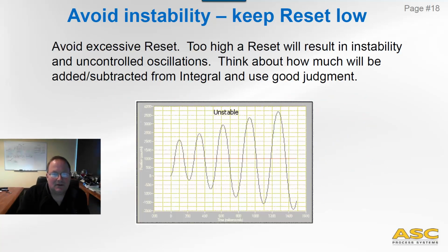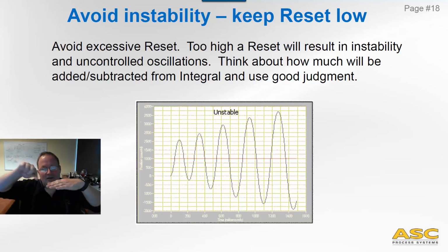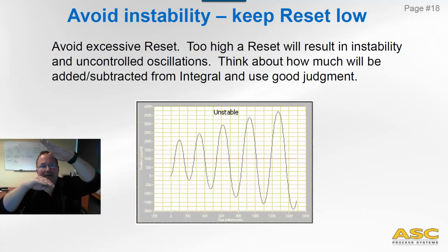What's another consideration? Keep your reset low. Reset is the integral gain. If you have a very high reset, what's going to happen is if you're below set point, you'll integrate that error, and it'll add to the output value, which is the I term contribution, which will then heat too much and you'll overshoot.